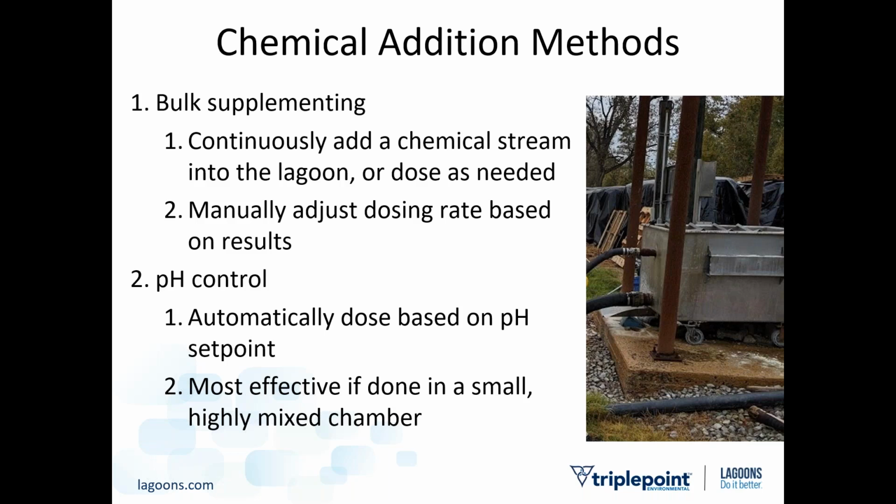They need to kind of supercharge nitrification in their lagoon for a little while. They add soda ash to their pond to raise the pH up into the really effective range, and they help those nitrifiers speed up in the spring when they're still a little sluggish, to help them meet their lower summer ammonia limit.